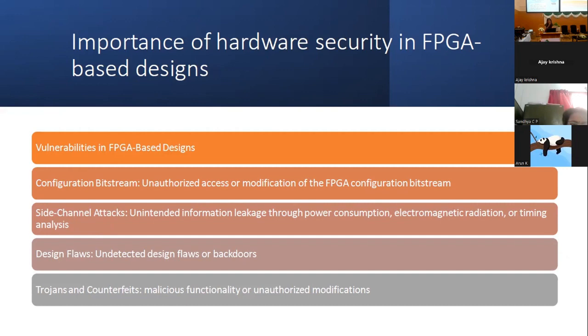Side channel attack means if hardware is executing, some properties of that execution we can capture. For example, how much power each operation is taking. By calculating that, we can find out which operation it is. Or if I'm doing an encryption, how much time it is taking for encryption. Based on that, I can guess the bit size, key size. And different types of side channels I will cover.